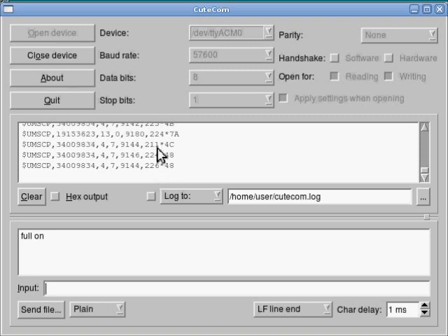So you'll see data coming in, depending on what the noise environment is like where you are running this receiver, at signal levels anywhere from 130 up. These transmissions are coming in from meters that are very nearby, and that's why these numbers are relatively high on the scale. So that's full mode. You'll get a little more information there about frequency and signal strength, which isn't essential for using the utility data, but is kind of interesting.